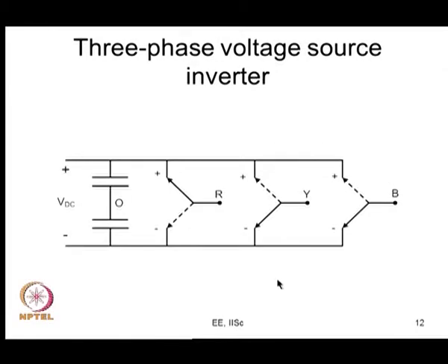What is the situation in a sinusoidal inverter? Here, 3-phase voltage, you desire a sinusoidal voltage between VRY, again you desire VYB. So, again between VBR you desire sinusoidal voltages. Like you can look at average voltage VRY average. What do you mean by VRY average? Averaged over a subcycle, and similarly VYB average is VYB averaged over a subcycle. We want these waveforms to be sinusoidal. You can ensure these to be sinusoidal if VRO average is sinusoidal, VYO average is sinusoidal, and VBO average is sinusoidal.